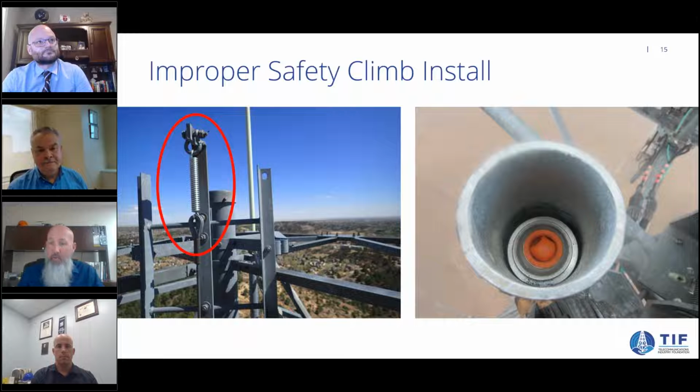The photo on the right is another example of a safety climb that's been installed improperly, because we still have the warding cap / debris cap installed inside of our strand vise, which means we know we don't have the proper depth of cable installed through the strand vise based upon what the manufacturer dictated for this safety climb.